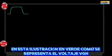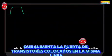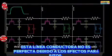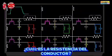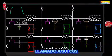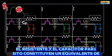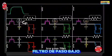Here is the reason. In this illustration, in green is represented the voltage VGH which feeds the gate of transistors placed on the same line. This conductive line is not perfect because of the parasitic effects, which are the resistance of the conductor and the presence of a parasitic capacitor between gate and source called here, CGS. The resistor and the parasitic capacitor constitute an equivalent of RC circuit low-pass filter.